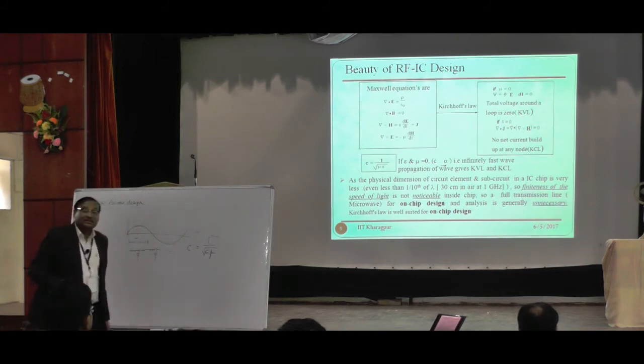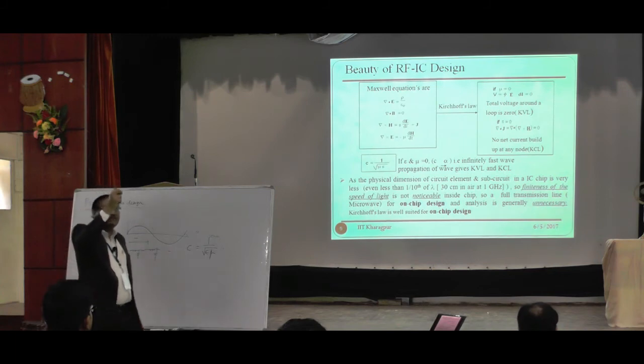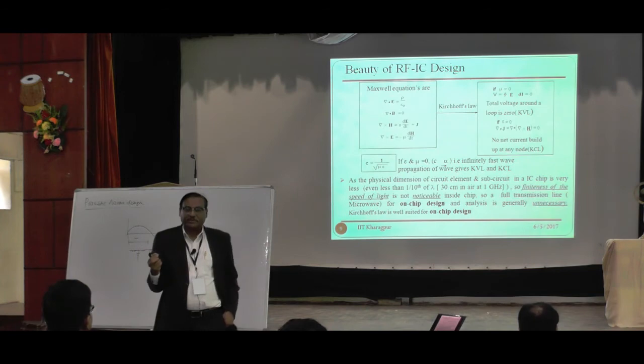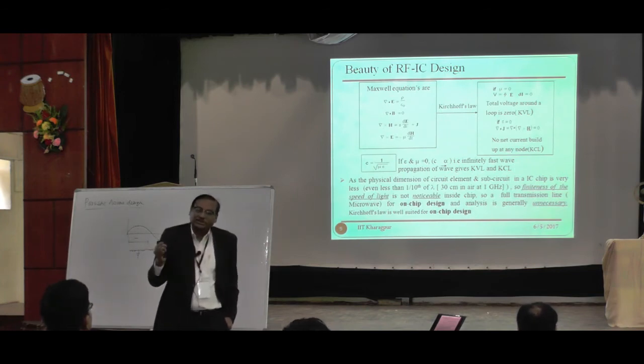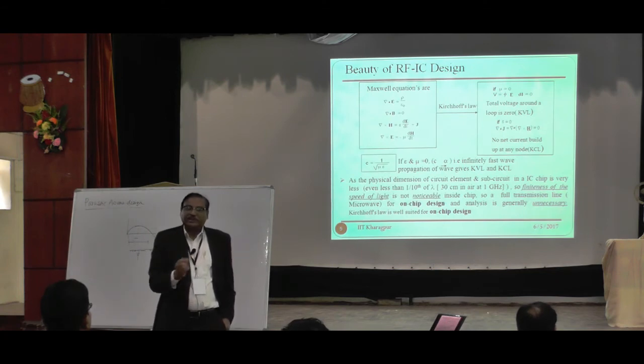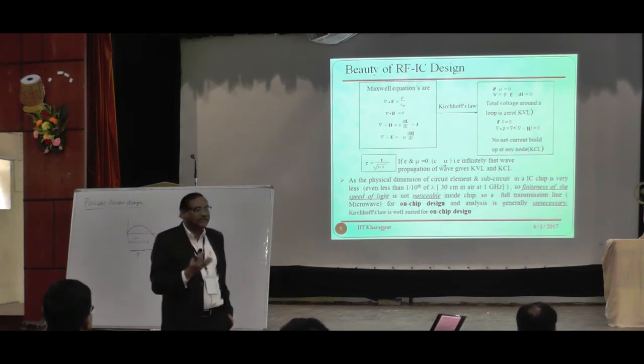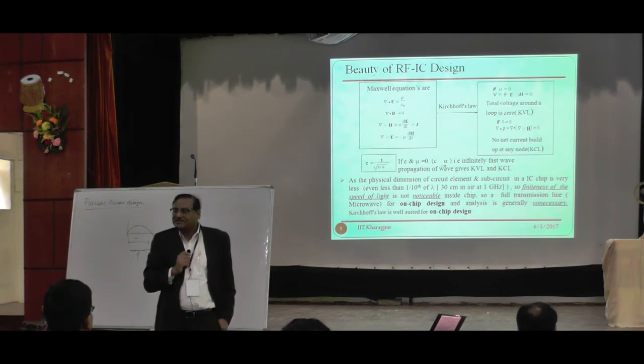But when I say that the electromagnetic wave, that is my signal, is not going to my device straightaway. It is captured by the antenna. It is processed through the filters. So those filters and antennas are not nanometer or micrometer size. Yes or no? They are the size of centimeters or millimeters. In that case, the wavelength is comparable to the size of the components. Then the phase difference would occur across the length of that.